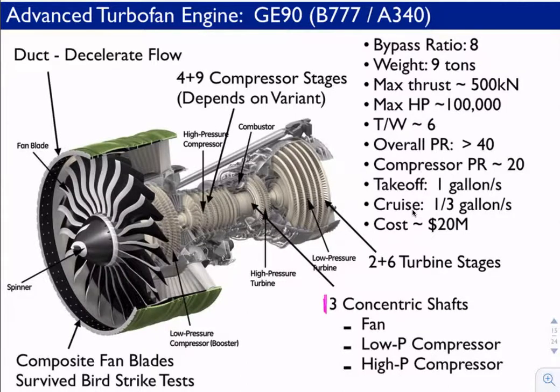But here you would have, for example, this turbine driving a late stage compressor, and these turbine sections driving an early stage compressor, and maybe these turbine sections driving the fan out here. So you have three concentric shafts, all spinning at different RPM, one inside the other, which already is getting incredibly complex. You have to deal with the bearings for that, both thrust and the bearings that hold them in place.